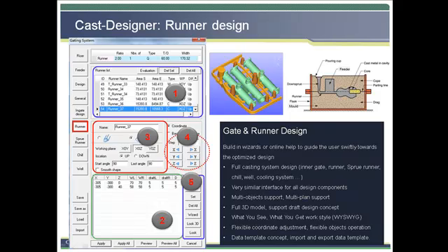The design method of the inner gate runner and runner is similar. Usually, the length of the runner is much longer than the gate runner, so Cast-Designer can pick up the predefined curve in an MCAD system directly and edit it freely. This is very useful for complex traces. Also, the runner tree could be generated by the system directly after the design.